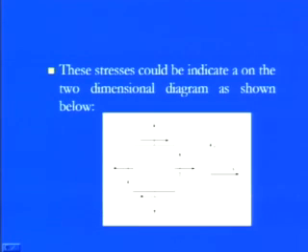These two directions show that the shear stresses tau yx are there, and they are always exactly equal and opposite to these stress components, and that's why we can maintain the equilibrium within these objects. The stresses are formed because of the force application, and under these stresses, the object is maintained in an equilibrium position only when the summation of forces in the x direction, y direction, as well as the z direction is 0.